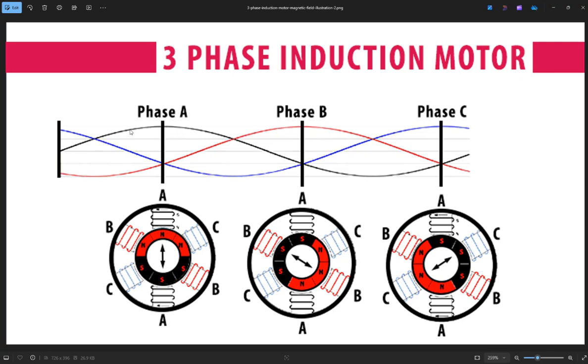Okay, so whenever it spins to here, then you activate it using a different phase, and then it starts pulling it towards the other direction, towards even forward, right? And then you activate this one, then it's generating another magnetic field, and then pulls it to the next. So that's how it's doing that kind of relay, keeping the rotor rotating inside the motor continuously. So that's why you need the three phases.